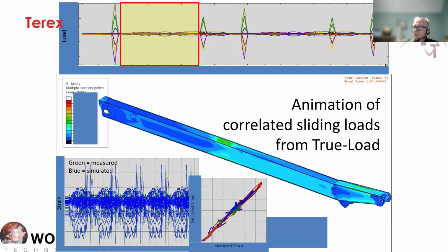Through a lot of work with my customer, I found out that at certain locations, at certain configurations of this crane, the crane is passing through a buckling mode. So we're passing through this buckling mode and getting a spike in the strain response. Since we only had linear load cases to work with, it is leveraging those linear load cases and making sure that it can match the strains in those buckling events. These loads aren't real. These are buckling loads going on here.